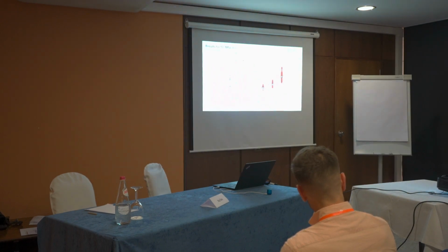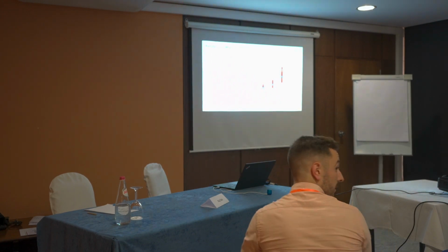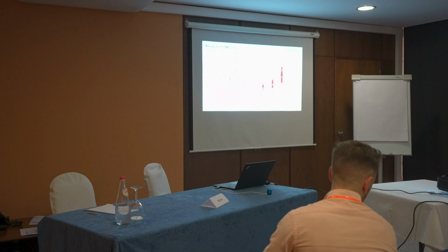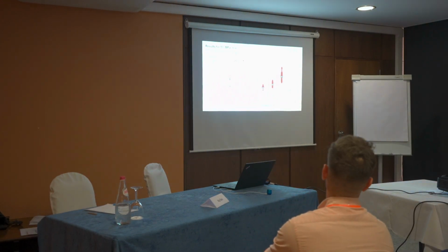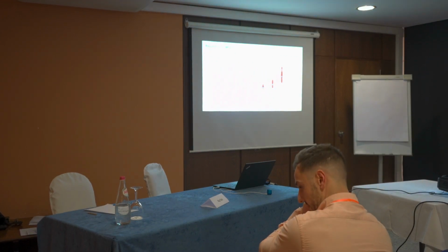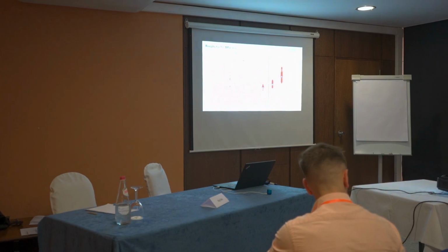And these are the results for a lower rate. 10 to the 3rd is not so very fast. For a 1T CT specimen it's only about 20 millimeters per second, so you can use standard clip gauges for measuring the COD. For the 10 to the 5th, you have to do optical measurement. And here you can use standard equipment if you have the correct bandwidth for your measurement.